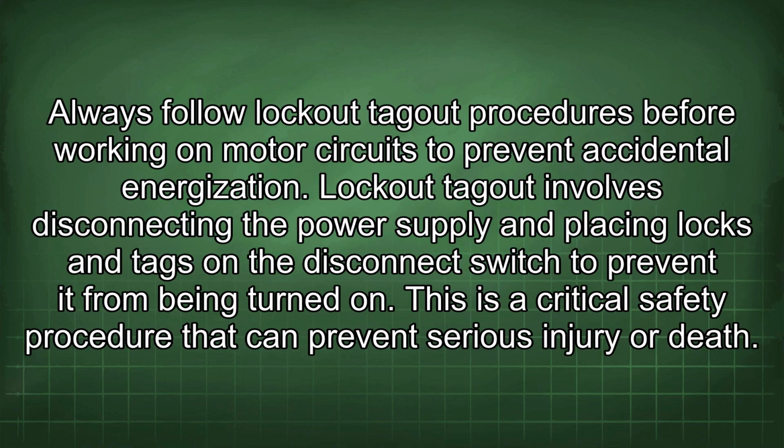Always follow lockout-tagout procedures before working on motor circuits to prevent accidental energization. Lockout-tagout involves disconnecting the power supply and placing locks and tags on the disconnect switch to prevent it from being turned on. This is a critical safety procedure that can prevent serious injury or death.